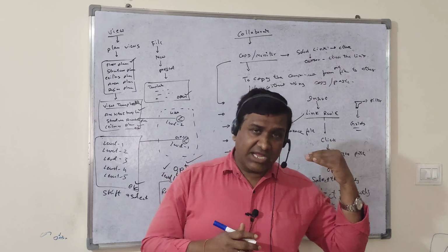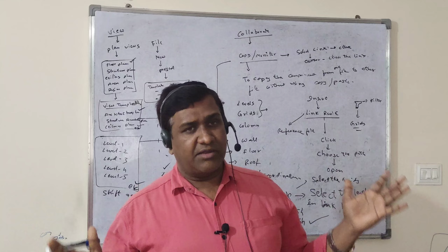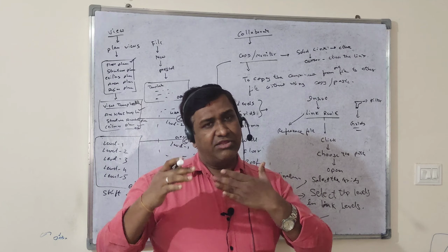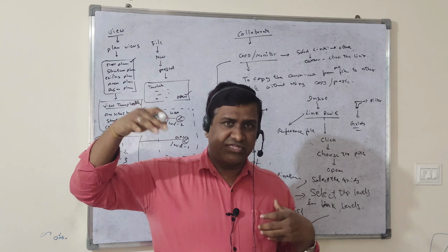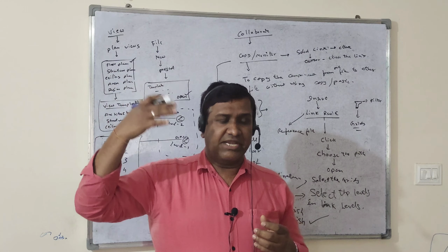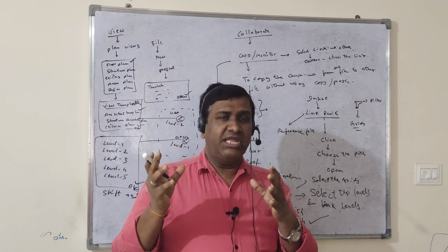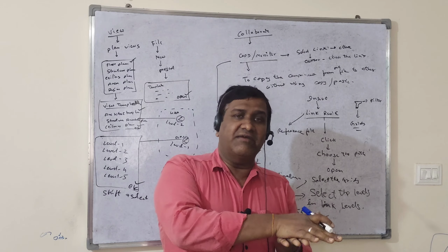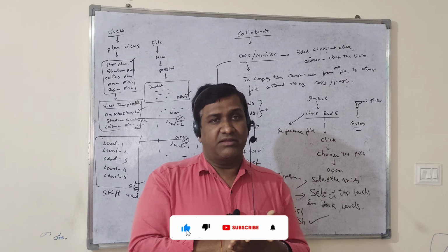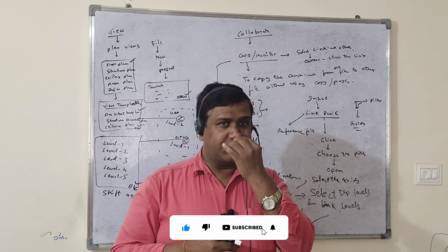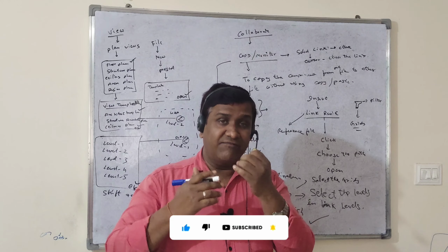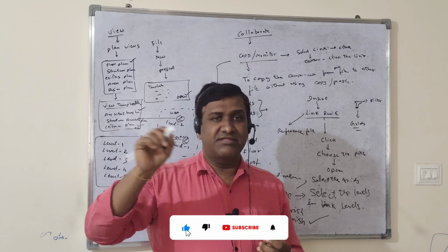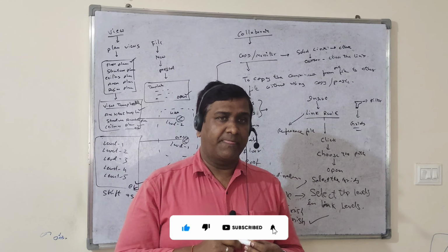So at that time they will tell their team, you start the project, you just create all the levels and grids, and start the project manually. When the architecture people give the architecture model, then you take those levels and grids and proceed further. But before that, the MEP team will start the project by looking at the AutoCAD structure file, the grids, levels, everything, and follow the same.